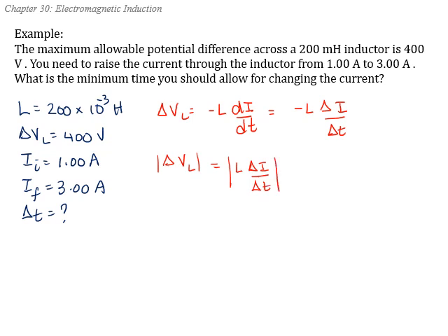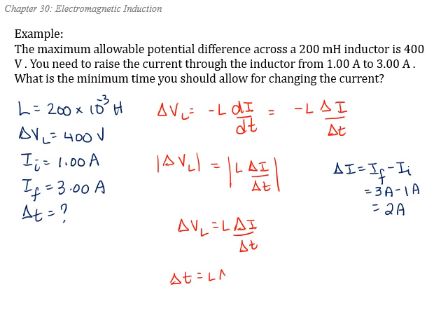Okay, what is our delta I? That's our change in current. Delta I is I final minus I initial. 3 amps take away 1 amp equals 2 amps. Okay, everything in our expression here is positive. So we can say delta V is L times delta I over delta t. You can solve for delta t equals L times delta I over delta V.